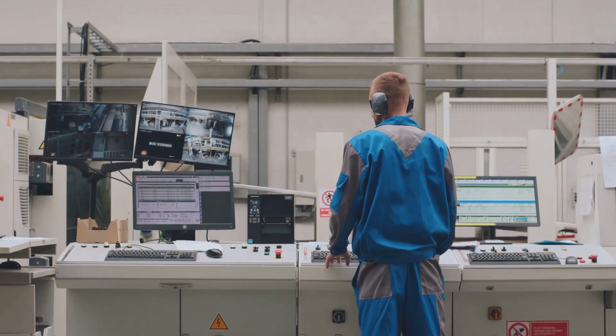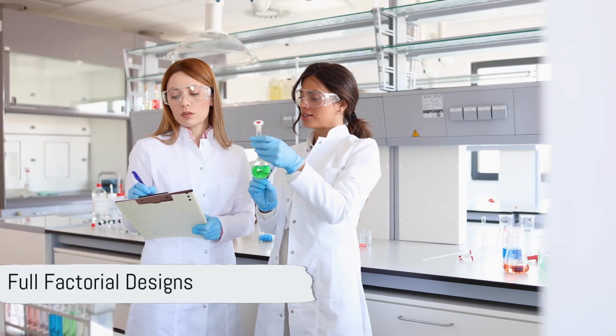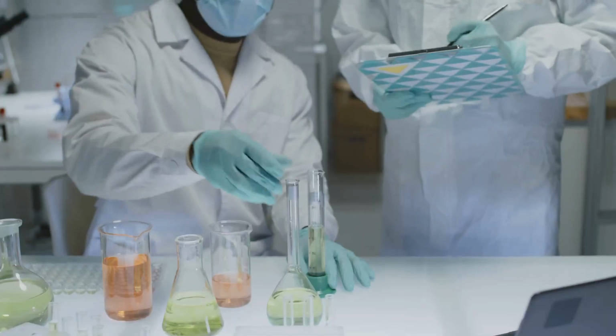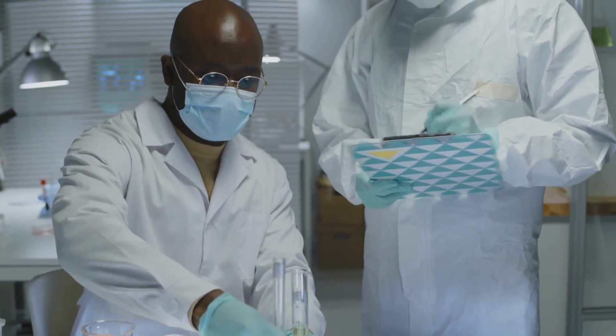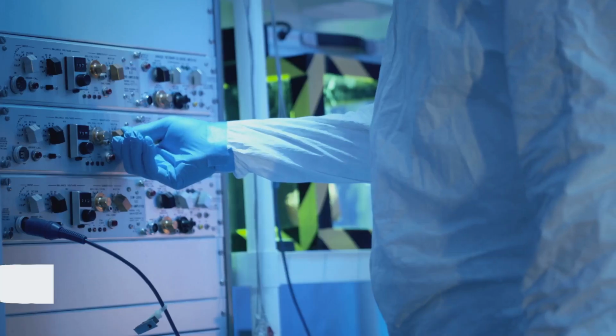There are different DOE structures to match your process complexity, resources, and goals. Full factorial designs. This is like the 2 cubed example, but tests all combinations. Best when you have a small number of factors and need full insight. Fractional factorial designs. Tests only a carefully selected subset of combinations. Great when you have limited time or want to screen for critical variables.